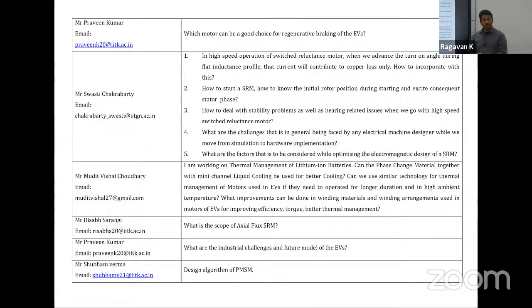But in terms of implementation details, you definitely will have losses in most cases. The simulations are too ideal. For example, temperature change, a lot of the secondary effects: you're running the motor and it gets hot and the winding resistance changes, your simulation never sees that. Your hardware will see that, which means there are changes, and your control will not adjust. So you have to start aiming towards robustness as you're operating, no matter which motor you're looking at. Generally speaking, you want to have more control than the system does. Otherwise, it'll be challenging.